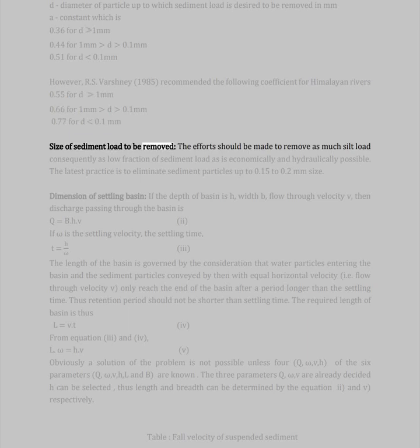Size of sediment load to be removed. The effort should be made to remove as much silt load, consequently as low a fraction of sediment load, as economically and hydraulically possible. The latest practice is to eliminate sediment particles up to 0.15 to 0.2 mm size.